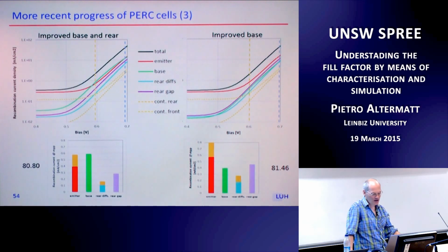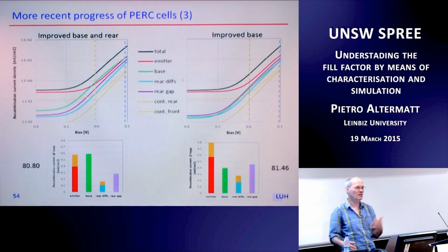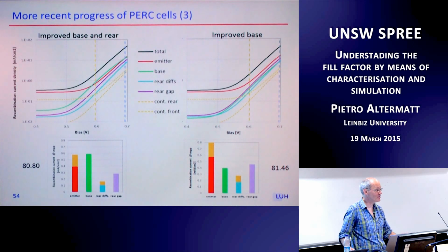No, the advantage in simulations is you get a voltage dependent picture of things. So you would also need probably, it would have an advantage if you wouldn't just do a PL analysis at MPP, but actually voltage dependent to see the dynamics. Yeah, of course. But if you have a lifetime, for instance, an injection dependent lifetime curve, you can basically plot that curve for the base, the green curve. Well, if you know the injection density in the cell, but that's what you probably know via PL then, yeah.